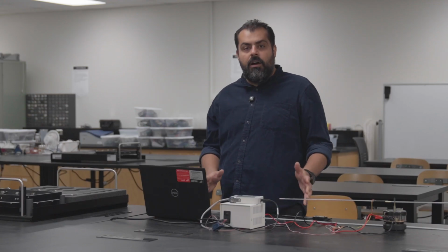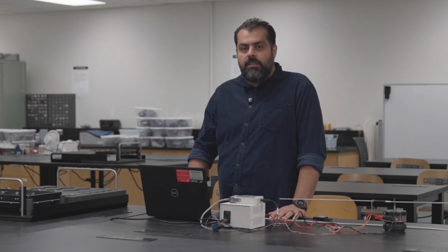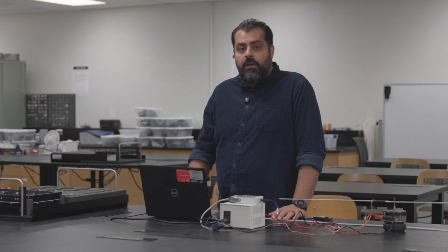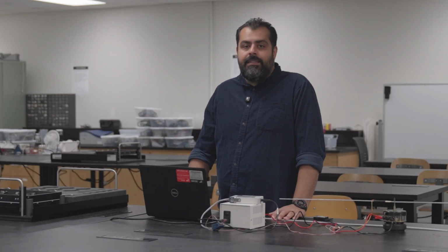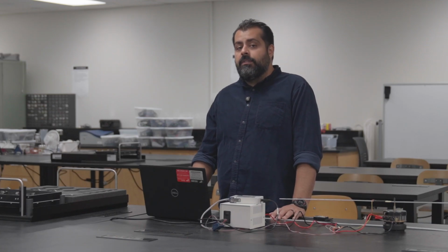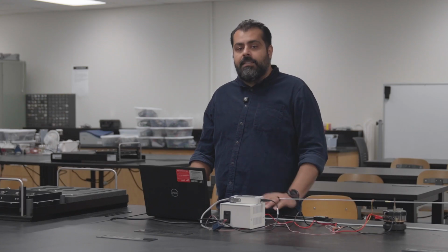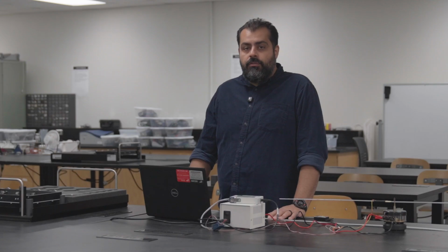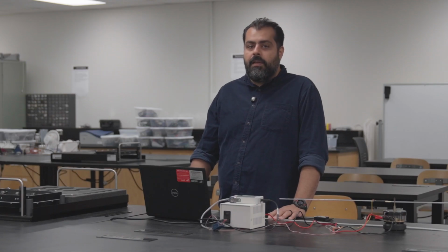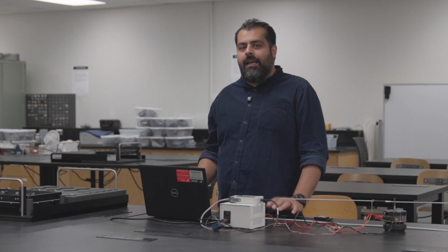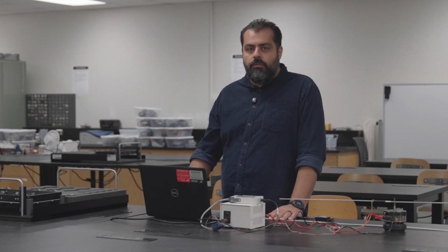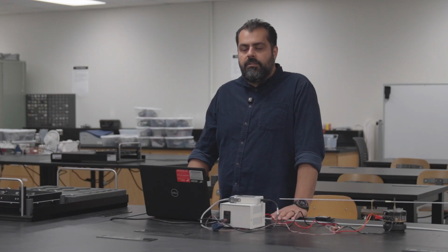The second part of the structural dynamics lab is going to focus on vibration analysis. In the vibration analysis part of the lab, we are going to focus on relating the location of vibration nodes, which are the locations where we see zero lateral displacement, to the natural frequency of the beam. And we are going to apply two different theories to the same experiment to see which theory actually yields a better result. And these are theories that are developed based on the mathematical relations of vibration.